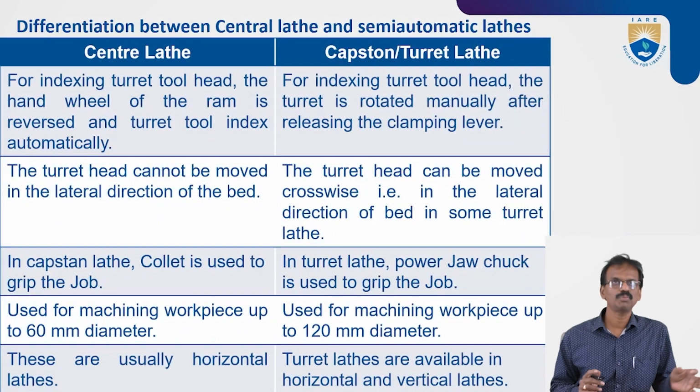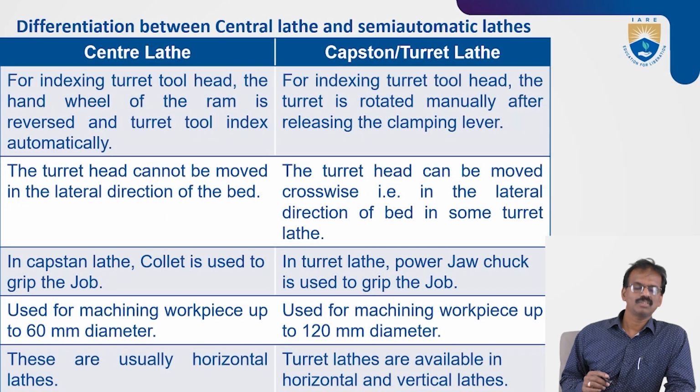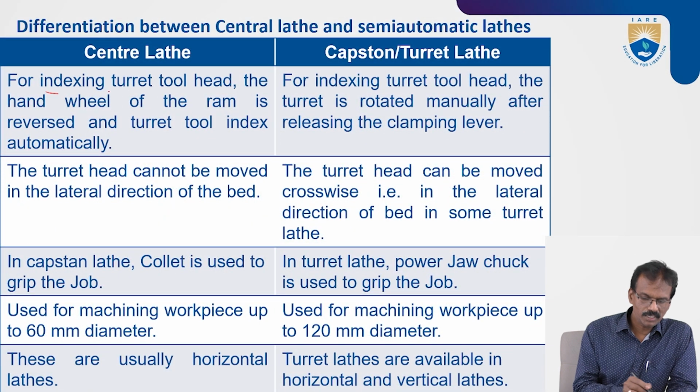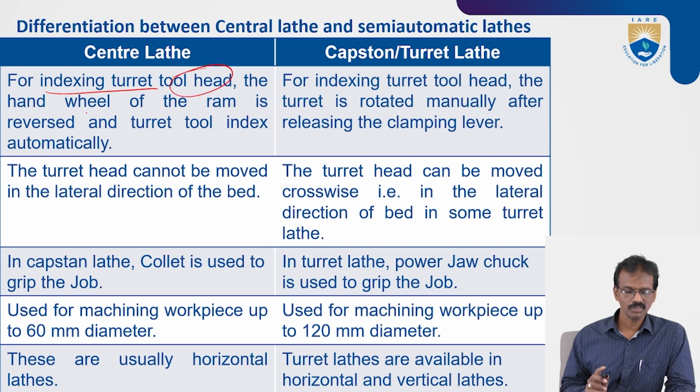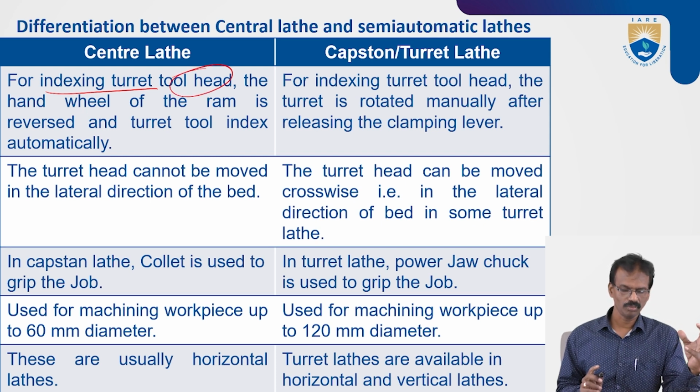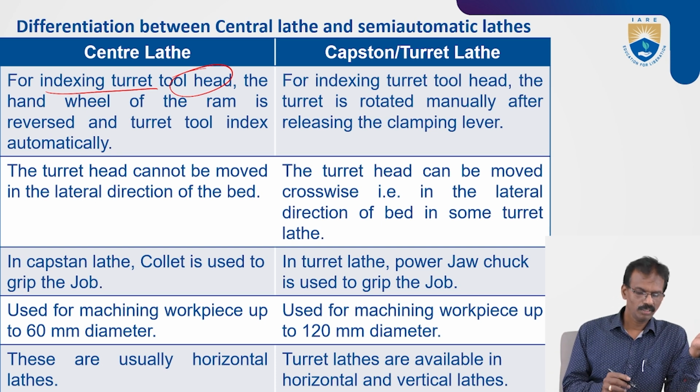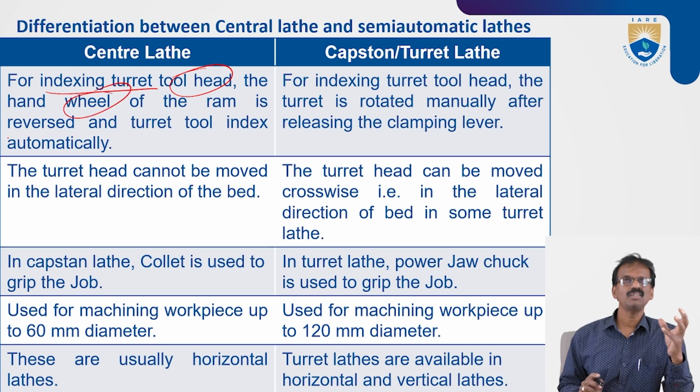A few more differences are given here. For indexing the turret tool head, indexing means positioning the next tool against the workpiece. The indexing turret head is operated by the hand wheel of the ram.